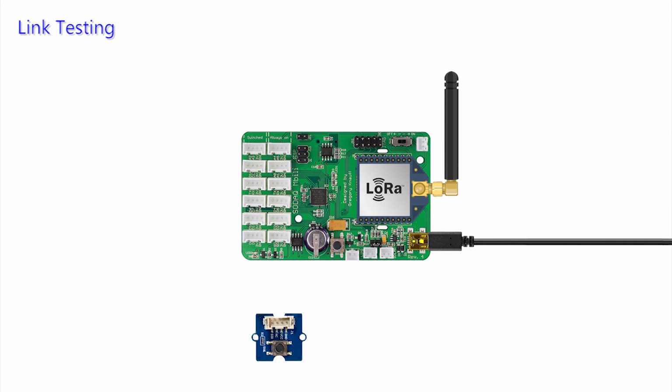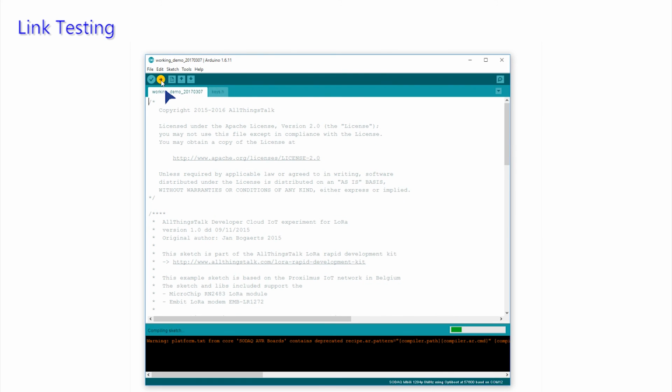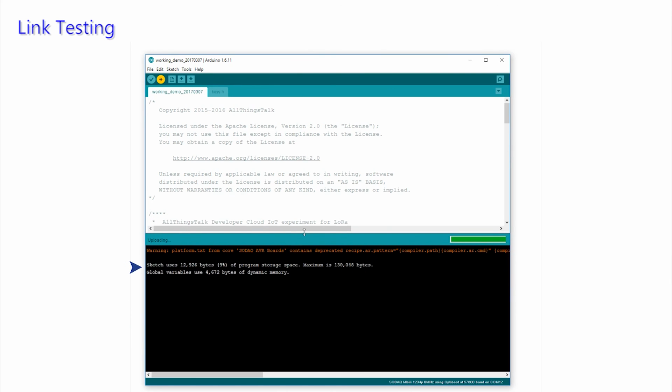Connect the button board to the socket shown. This may be done without removing the power. As a note, Arduino devices do store their last program even after the power has been removed. We are ready to proceed by pressing the arrow key and checking the upload progress bar. Again, this orange warning may appear, but this is a short-term issue that can be ignored. Any red text here needs to be investigated, but white text indicates that the program has been compiled correctly and